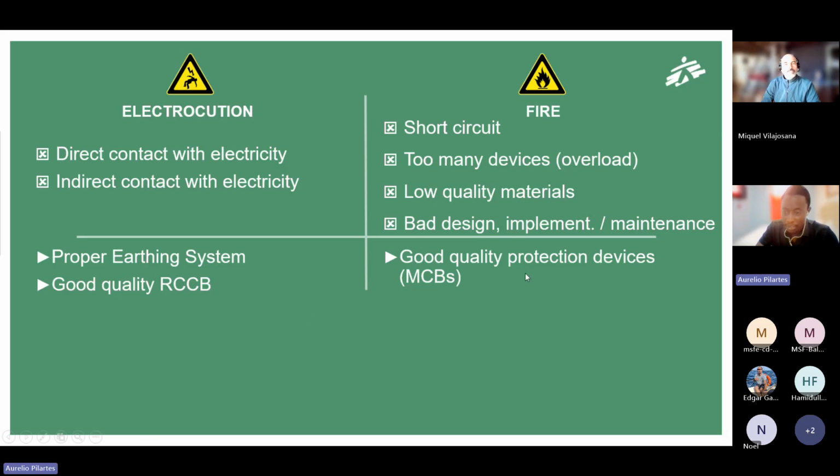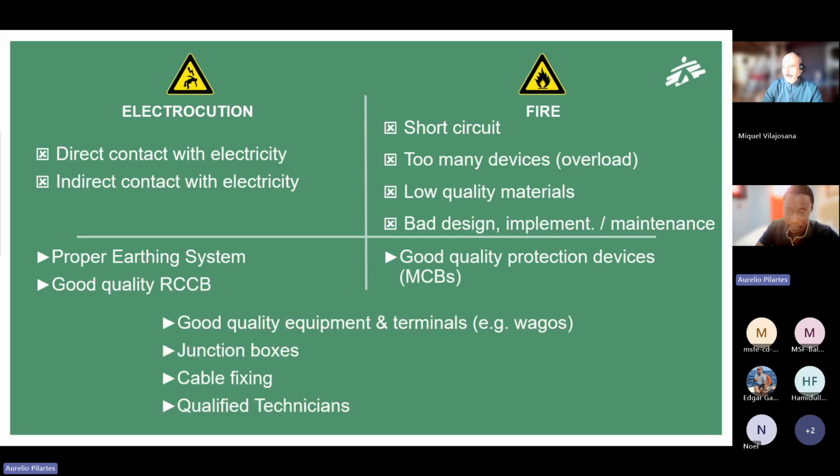Also, good quality protection devices and good quality MCBs to always trip whenever there is overheating of a cable. The MCB will trip before some fire starts. So we should always have good quality MCBs, good quality equipment and terminals.